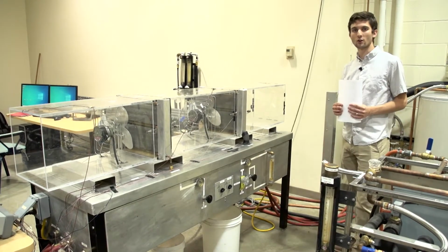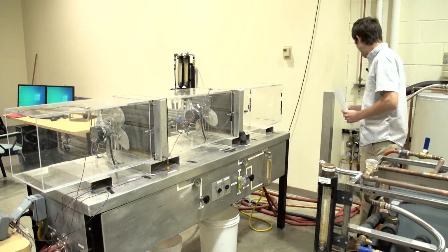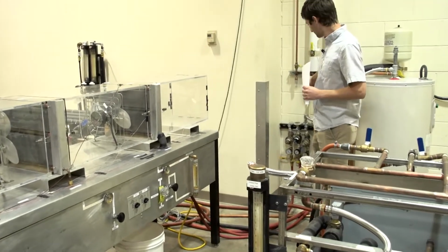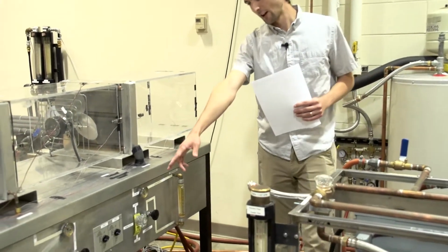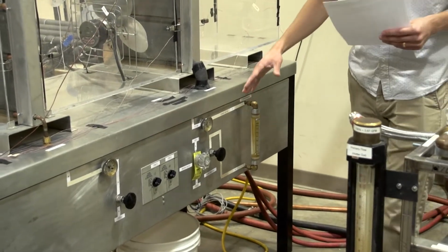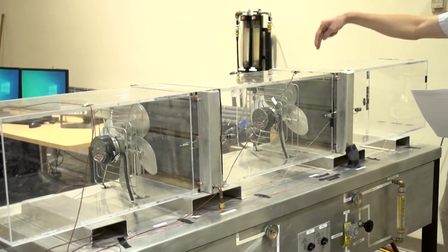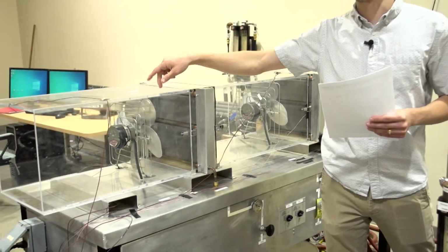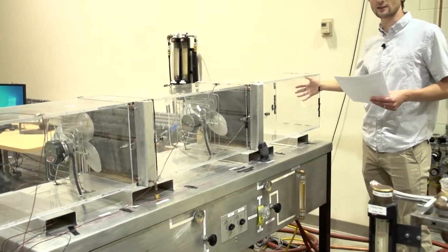So just an overall explanation of how water flows through this experiment. We start with the cold and hot water flow manifolds at the wall. Hot and cold water enter the system via hoses, and then you control the flow rate as well as the hot-cold mix. Cold water flows through heat exchanger 1, and hot water flows through heat exchanger 2. Meanwhile, you have the fans controlling airflow through the wind tunnel to the exit at this end.